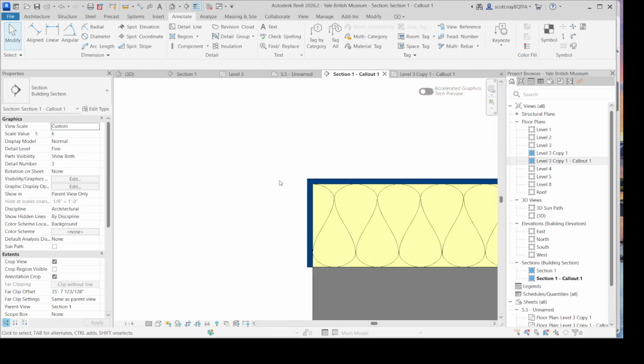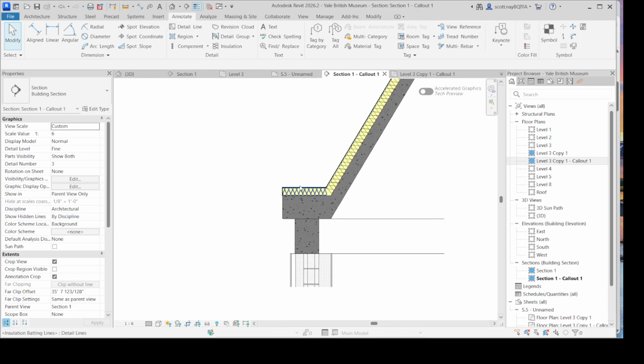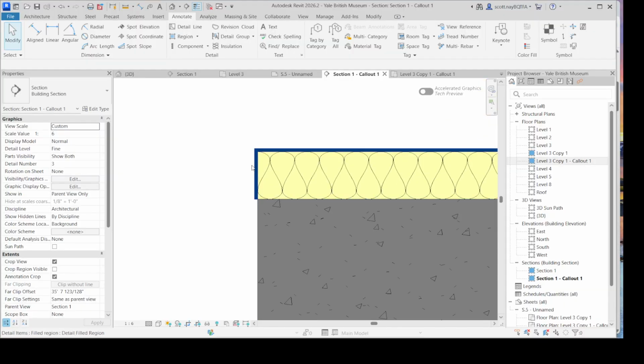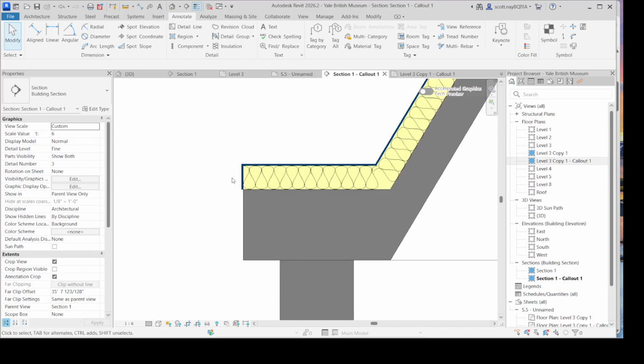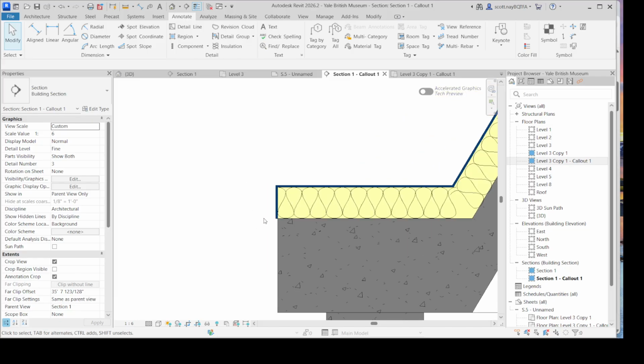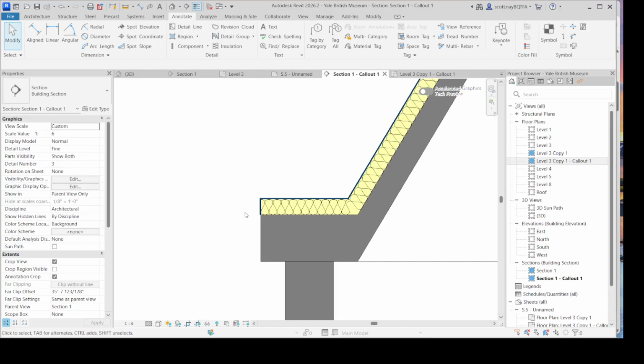Alright, so what's left for this is the flashing. So I'm going to start it pretty far back. If you've never seen flashing, it comes down and then it comes out at an angle because water will follow the curve and it will come right down this surface and wrap along the bottom. So you need to give a drip edge that forces it. It can only come back so far before it falls down.